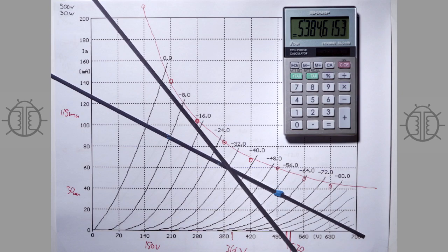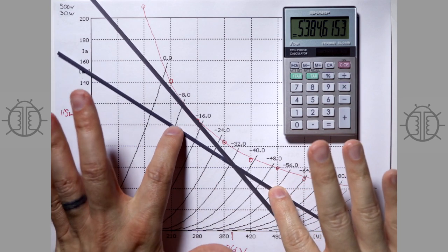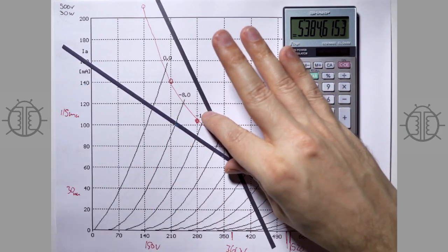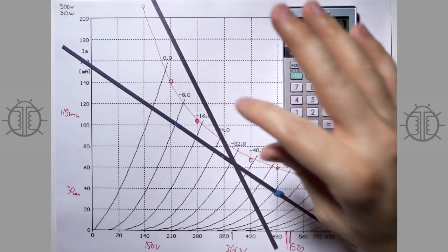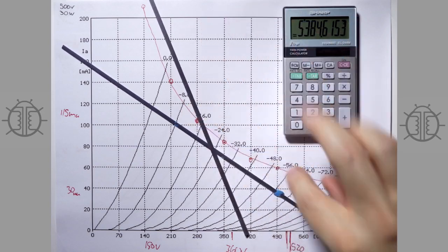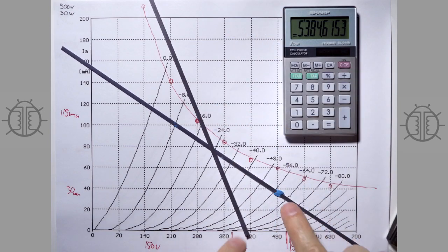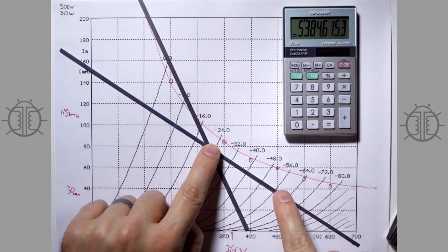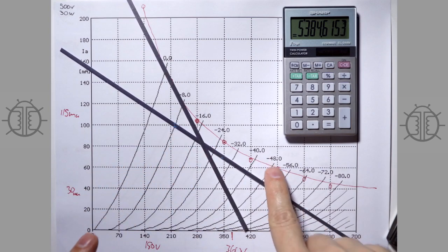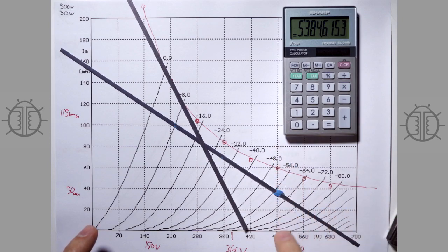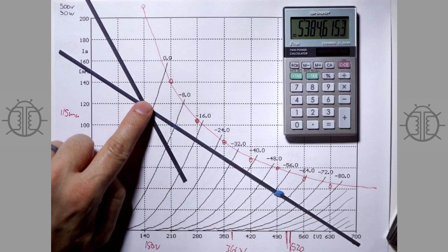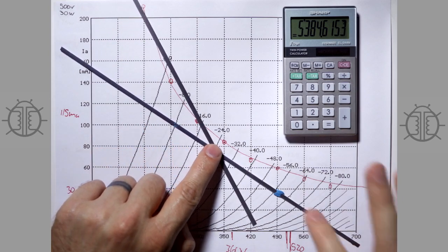And so if you wanted to go, for instance, an 8K plate to plate, that would be 4K and 2K. And so you can see what that would do. It would kind of go up like this, and then this would kind of go up like that, and that's not so bad. You're getting pretty close there. Now, if you wanted, I think this moves up like this because we moved our bias point up. And so we can swing a little bit further before we go into Class A. And I notice that the hotter you bias this, the further your Class A moves up. And so if you biased it hot enough, and in this situation with this voltage it would be past max dissipation, you go straight into Class A again. It never gets to Class AB. So you can kind of see how that works.